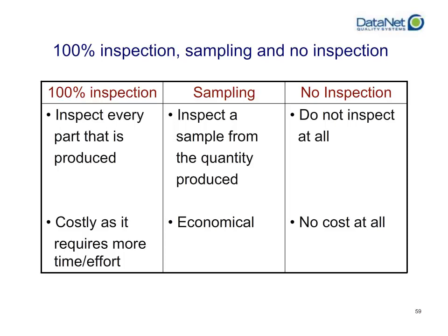So now that we've talked a little bit about the types of control charts you might see, we're now going to talk about how often you want to collect data and put it onto a control chart. There are three general categories of inspection sampling rates that you can use in any given process. Your first option is to inspect everything, 100% inspection. Another option is not to inspect anything at all. And then there's sampling, where you inspect some representative sample. There are advantages and disadvantages to all of the different options, and we'll cover that right now.